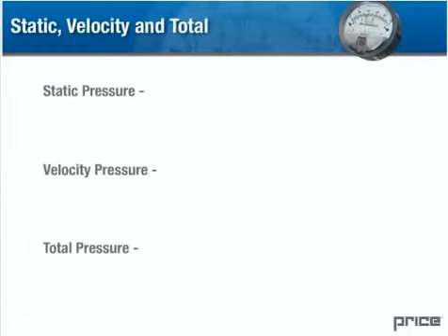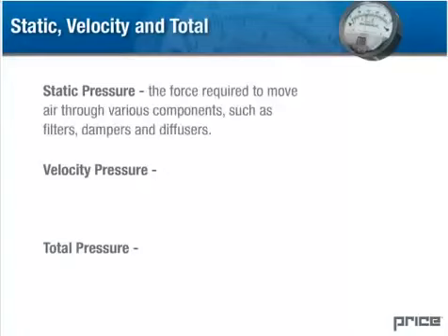These three types of pressure are associated with HVAC systems as well: static, velocity, and total pressure. Static pressure in an HVAC system is the force required to move air through various components such as filters, dampers, and diffusers. Static pressure is exerted equally in all directions.